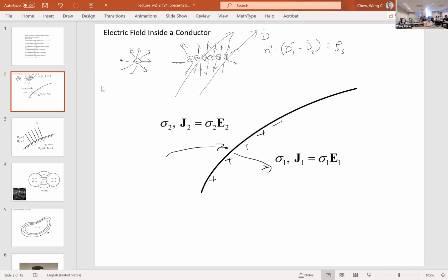Another boundary condition that we have derived mathematically, but based on the intuitive notion that if you have a piece of wire carrying a current, the magnetic field that you would have would look like that from your undergraduate courses. Okay, so if you have a line of currents lined up to make up a current sheet, the magnetic field will look something like this intuitively. You can see that the magnetic field H1 on one side and H2 on the other side are of opposite polarity.